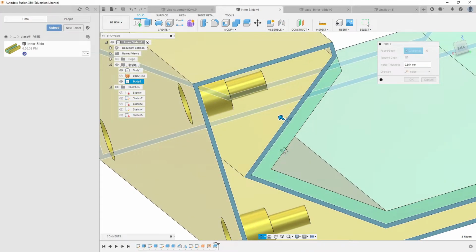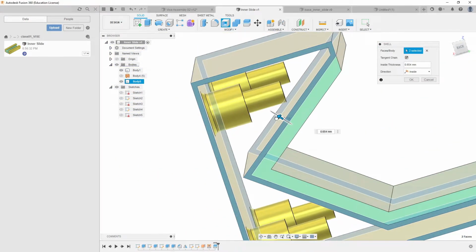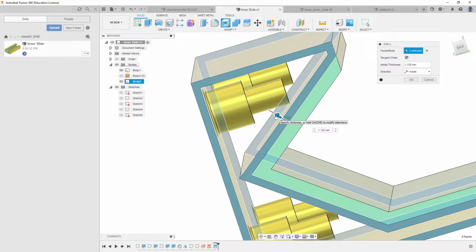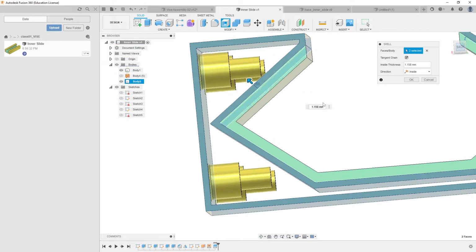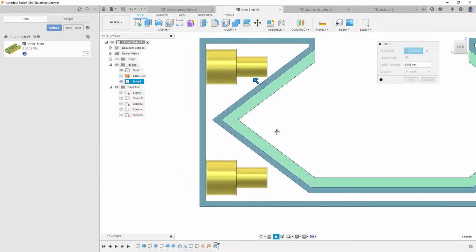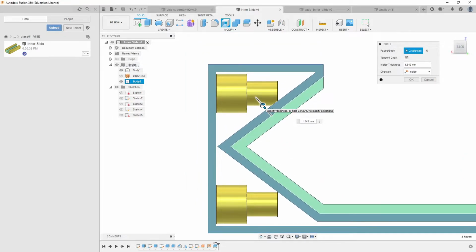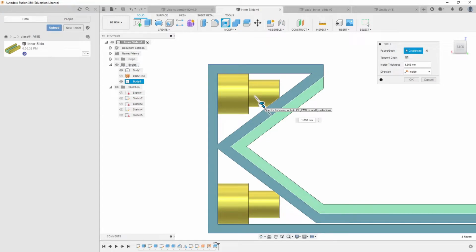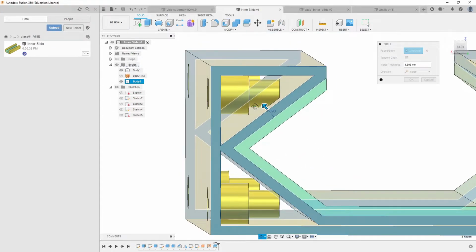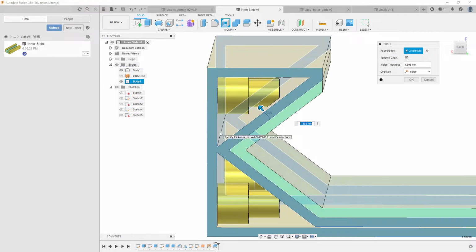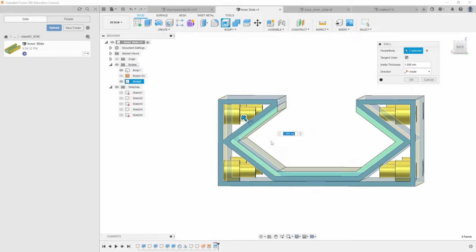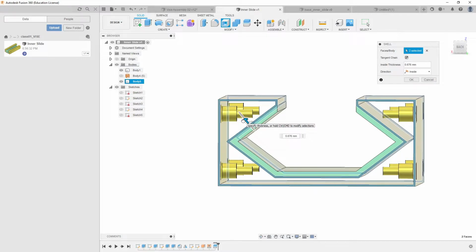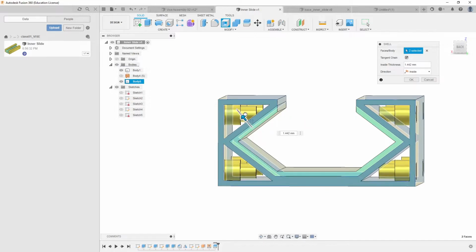So how thick do I want this to be? Well, you would be inclined to say, well, thick enough to be strong. Okay, that's totally reasonable. But I would add on to that, since this gap distance here is probably not much more than 1 millimeter, if I bring this up a little bit more until maybe they're touching a touch, then what I can do after the fact, now that they become one here, I've got an edge that I can add a fillet, and then I could definitely reinforce that a bit better, and I've got a better structure overall. If I leave it kind of thin like this, not touching, you can kind of see how this could wiggle around a little bit. We might have to actually add structure later to help reinforce it.